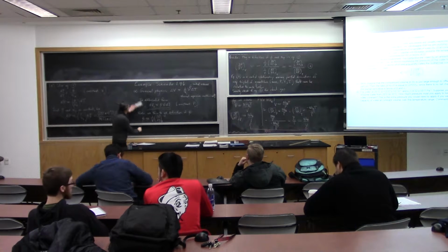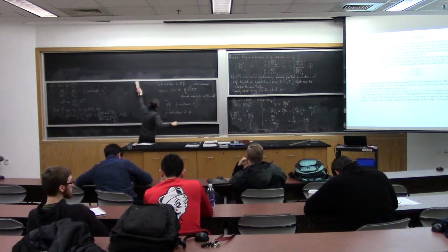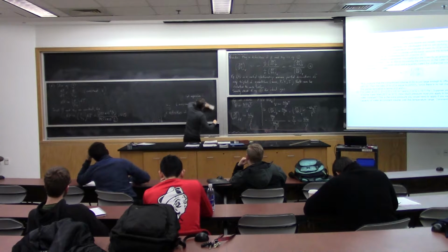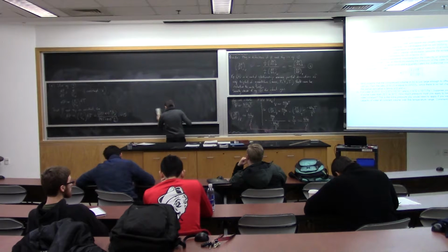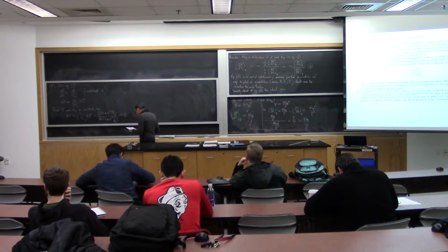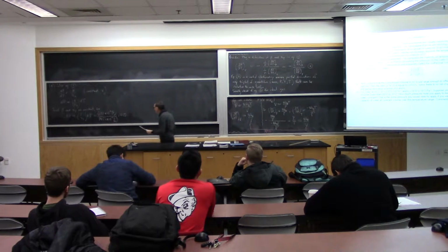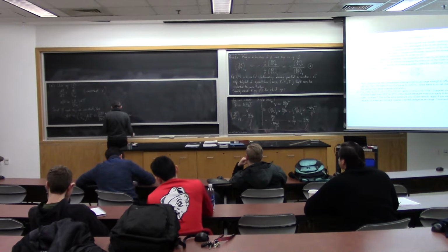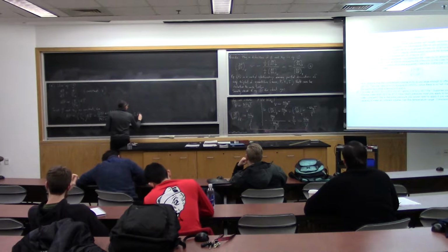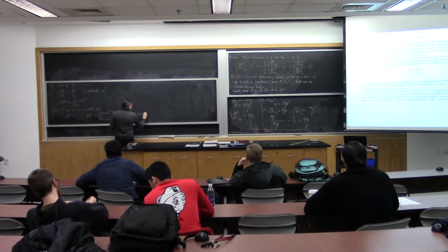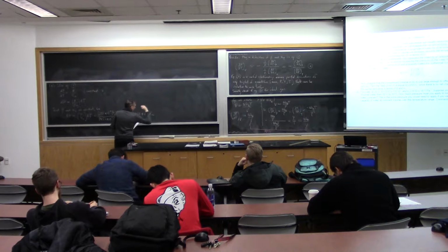The units of Celsius degrees are going to cancel. The final result is going to have units of pascals, which it should because I'm solving for pressure. And the value I get for the pressure you need to supply to keep the water from expanding, to keep its volume constant, is 5.69 times 10 to the 6 pascals.